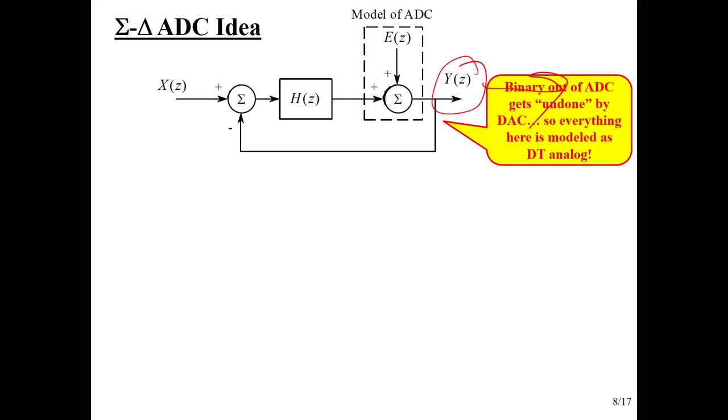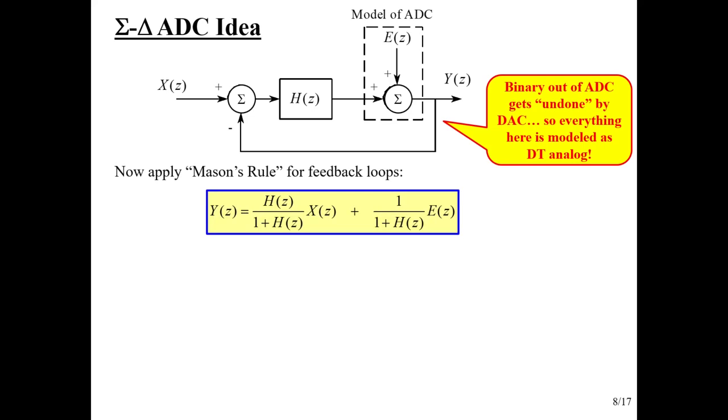We know how that works. My focus is to try to figure out what I need that to look like and figure out what the spectral densities, power spectral densities look like at the output of this structure before I go into my filter and decimate. So I've got a system here. It's all nice and analog, even though I've got H of Z's in it. So I can model it just with regular H of Z analysis.